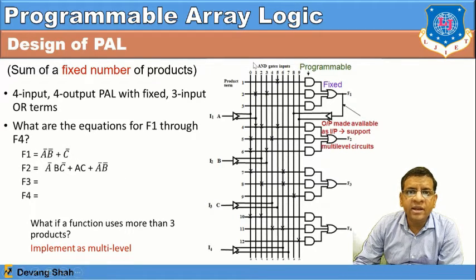So this is an AND gate input where you can see all these gates are available, and you just make it programmable. So this particular array, or this particular matrix, is available with the AND gate inputs, which are programmable, and these programmable AND gates are available with the fixed array of the OR gate, and that way you can generate the complete boolean function.